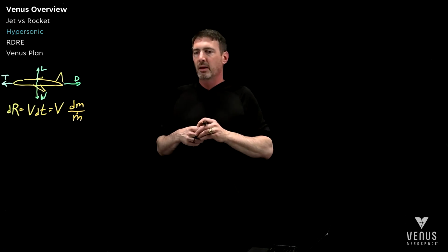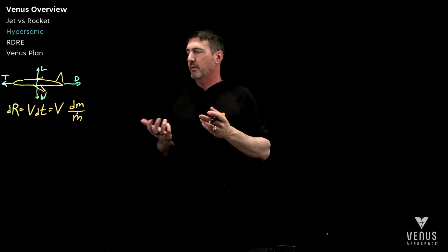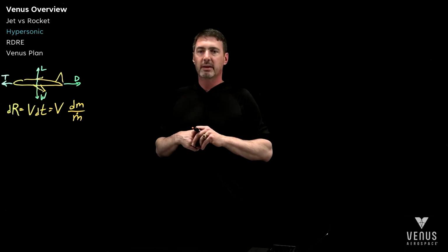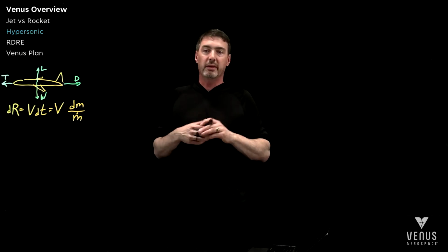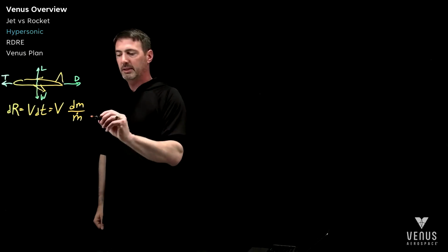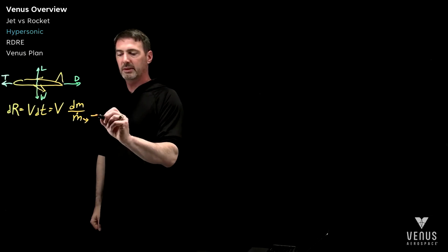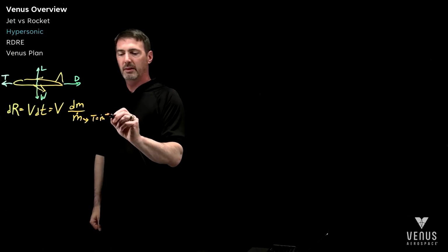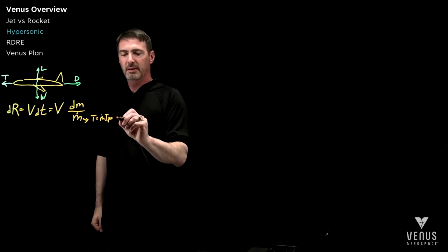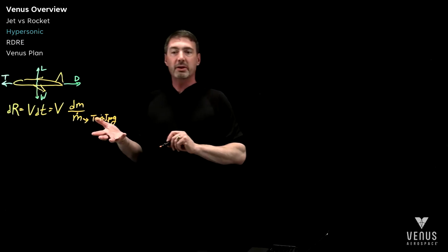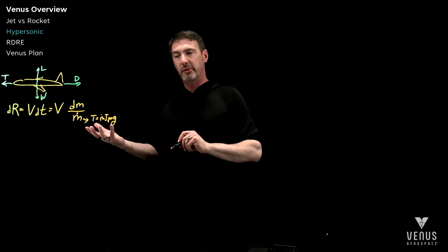segment. And so we can then think about the thrust of the aircraft because mass flow rate is related to the thrust. And so going back to the equation that thrust is actually mass flow rate times ISP times gravity, we have an equation for m dot, and so I'm going to substitute that in.